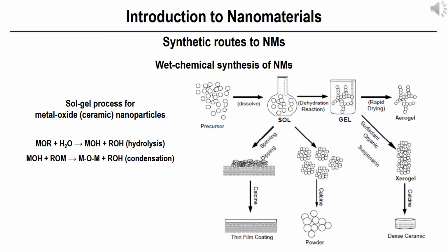The major difficulties to overcome in developing a successful bottom-up approach are controlling the growth of the particles and then stopping the newly formed particles from agglomerating. Other technical issues are ensuring the reactions are complete so that no unwanted reactant is left on the product and completely removing any growth aids that may have been used in the process. Also, production rates of nanopowders are very low by this process. The main advantage is one can get mono-sized nanoparticles by any bottom-up approach.